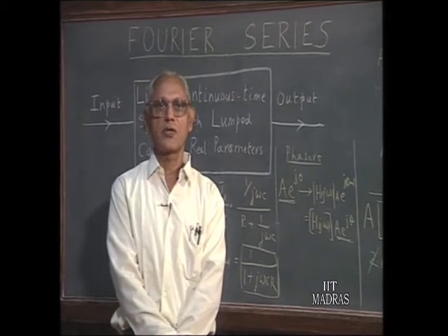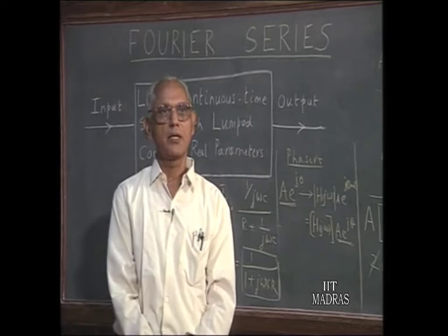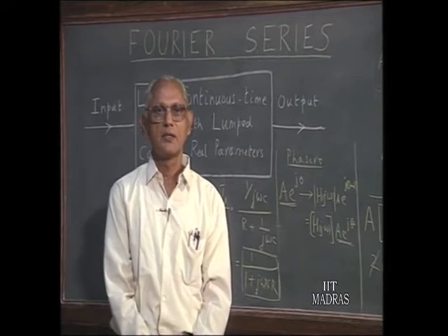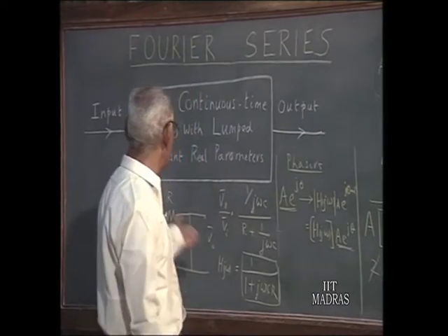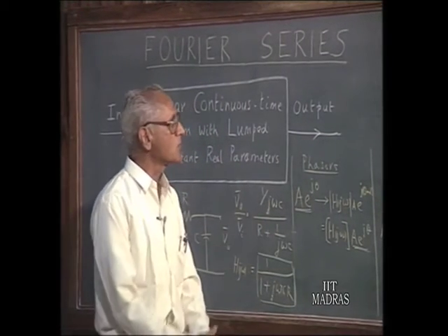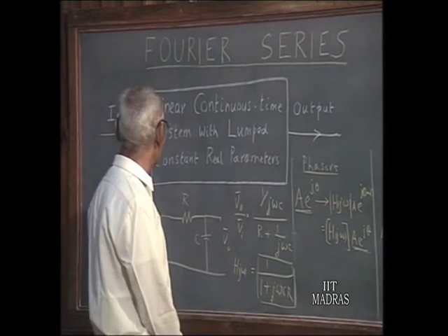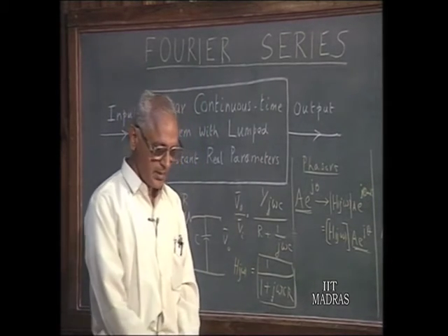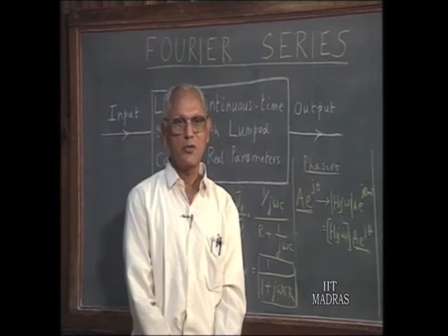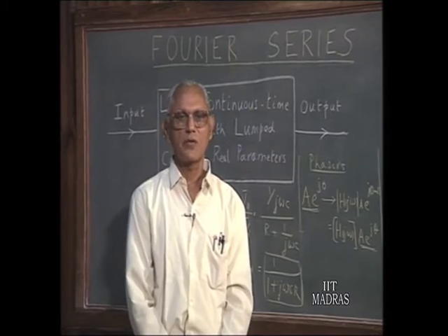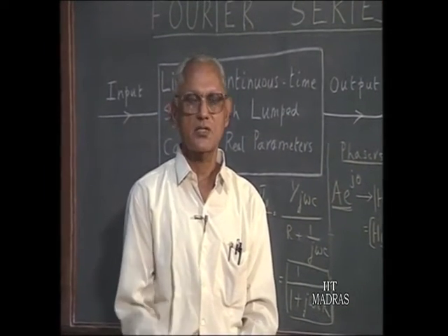Not only can sinusoidal functions be easily generated in the lab, but the input-output relations can also be quite conveniently measured. This is not possible with exponential signals, particularly when s is complex. Of course, it is impossible because no physical signal will have that. But even if s is real and F is real, you may have a decaying exponential signal, for which you have to do some kind of photographing or recording process. You will not be able to take measurements under steady state conditions. So, this is difficult.